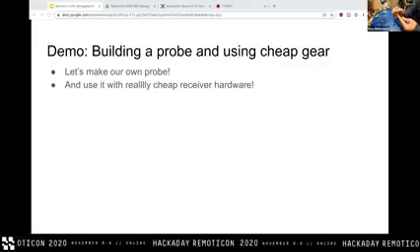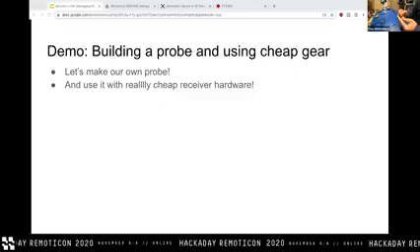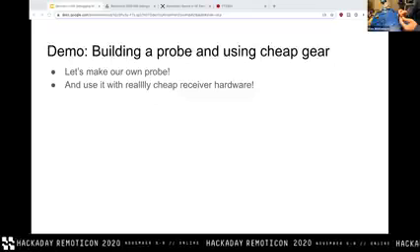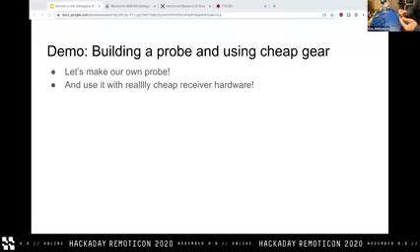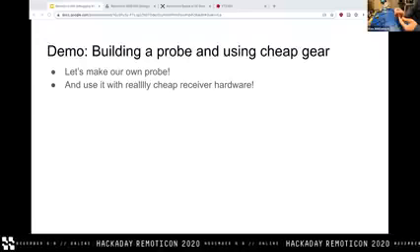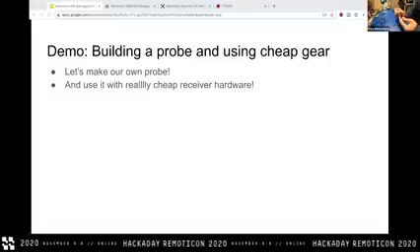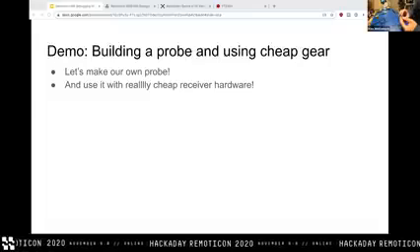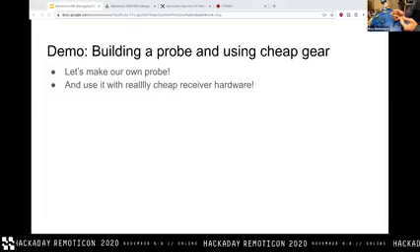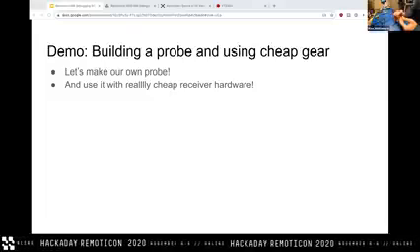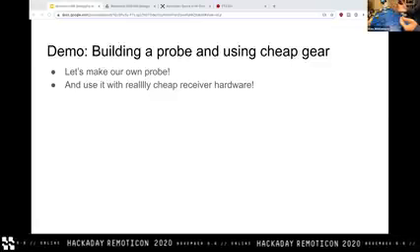That's effectively what we've done here by twisting this pair, is both minimize the loop area that's open to magnetic field and also make sure that any magnetic field affecting this open loop is immediately canceled by the adjacent open loop. And then the second half of this is, I think these pretty much just don't really require shielding to be useful, simply because they're like electrical short circuits at DC.